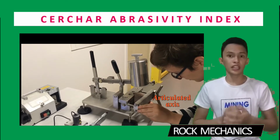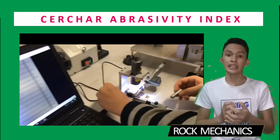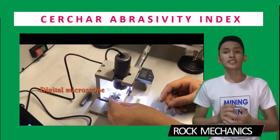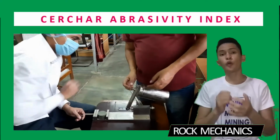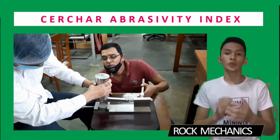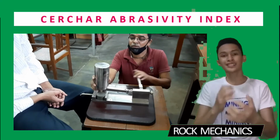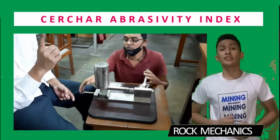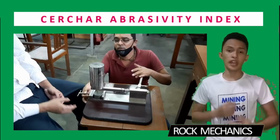The length of the test scratch in the rock sample must be exactly 10 mm. Depending on the apparatus designed, the testing duration is either 1 second for type 1 or 10 seconds for type 2 apparatus. During the test, there should be constant contact between the stylus and the rock surface. Otherwise, there is more likely to be an erroneous result and the test must be repeated with a new stylus.